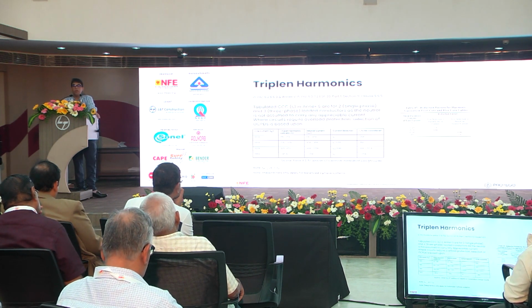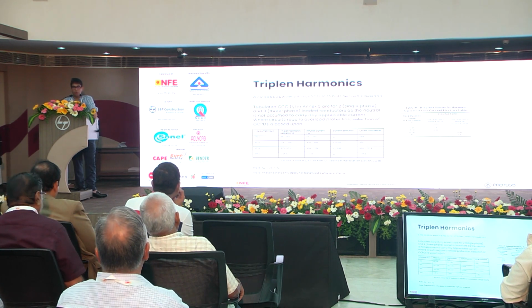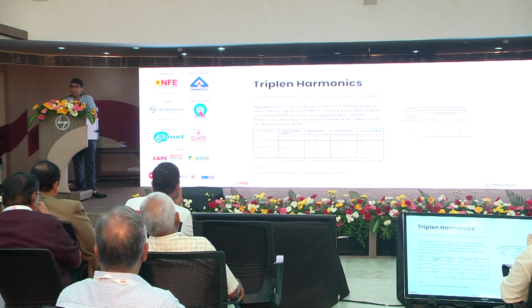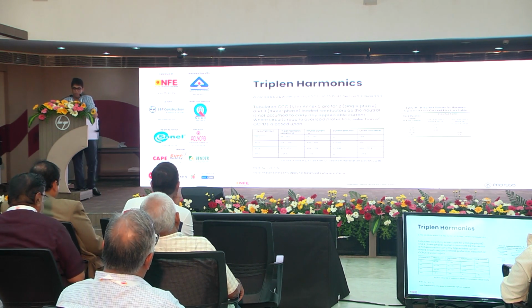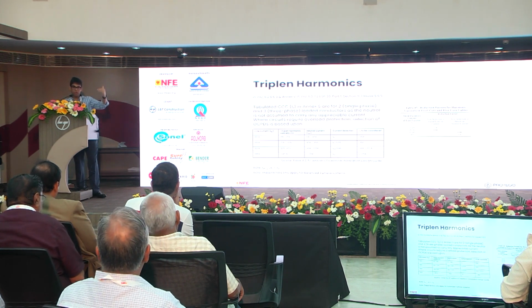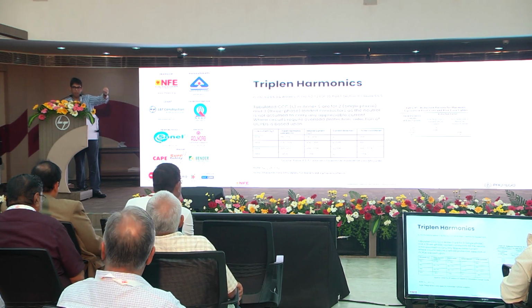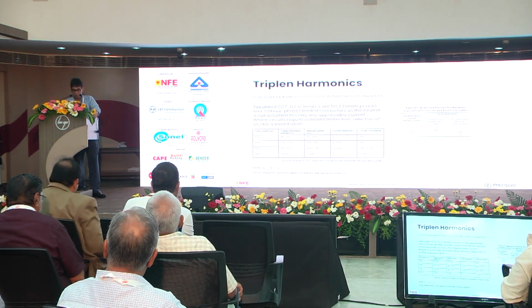Can anybody think of why? Why is it that in a technically more onerous situation, we are not applying a derating factor? Anybody? Okay, I'll give you the reason. It's because the neutral and the phases are going to be so oversized for the line conductors that the line conductor operating temperature is going to be nowhere near the maximum. Therefore, the effect of the heating can be not considered.